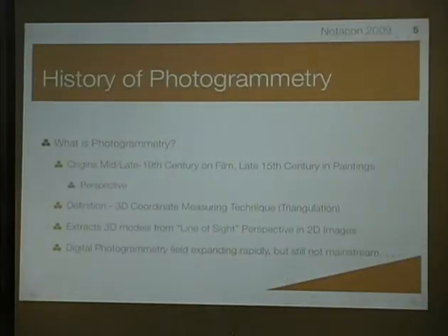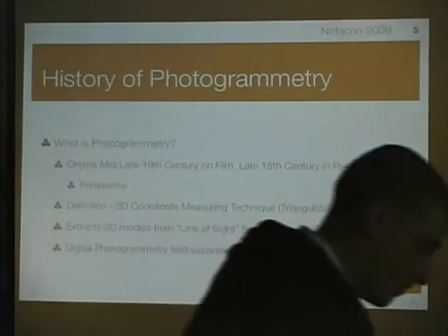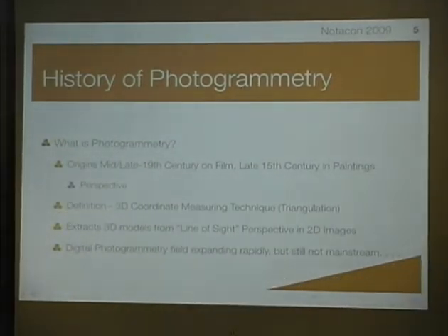Okay, so what is photogrammetry? From our point of view, as far as using technology to capture visual images, photogrammetry really got started around the beginning of photography itself, so mid-1800s. And it was primarily used at the time for topography and cartography purposes. So essentially, it uses a process of triangulation, right? So we would have more than one camera, generally 2 or 3 shots are a minimum.